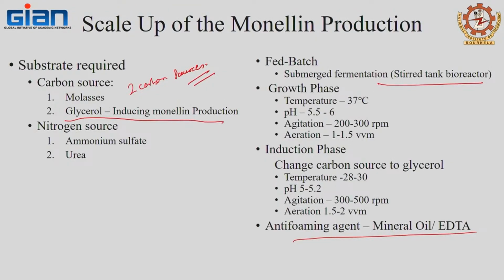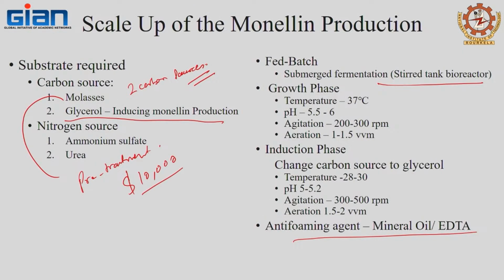So I think first we can go for pre-treatment of the molasses before using it as a substrate. That will reduce your impurities to a certain extent. Yes, it will increase the cost, but compared to using synthetic media, it will still be less if we use molasses. I understand that, but you're using two carbon sources. Yes, sir. So you're using glycerol just as an inducer for gene induction? Okay, fine. And then for the protein we have ion exchange chromatography plus ultrafiltration also.